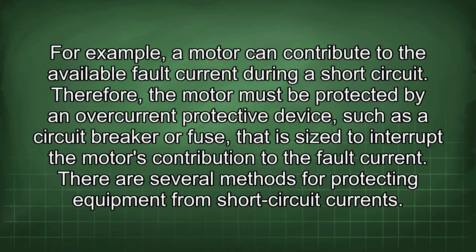For example, a motor can contribute to the available fault current during a short circuit. Therefore, the motor must be protected by an overcurrent protective device such as a circuit breaker or fuse that is sized to interrupt the motor's contribution to the fault current. There are several methods for protecting equipment from short-circuit currents.